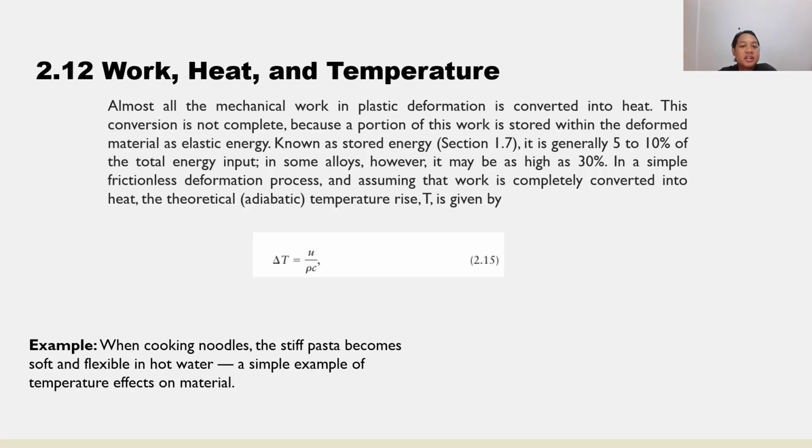Next, we have work, heat, and temperature. Almost all the mechanical work in plastic deformation is converted into heat. This conversion is not complete because a portion of this work is stored within the deformed material as elastic energy, known as stored energy. It is generally 5 to 10% of the total energy input. In some alloys, however, it may be as high as 30%.